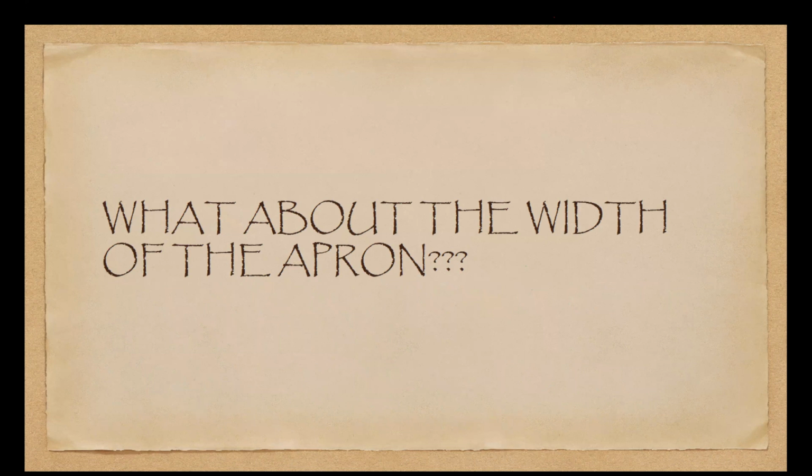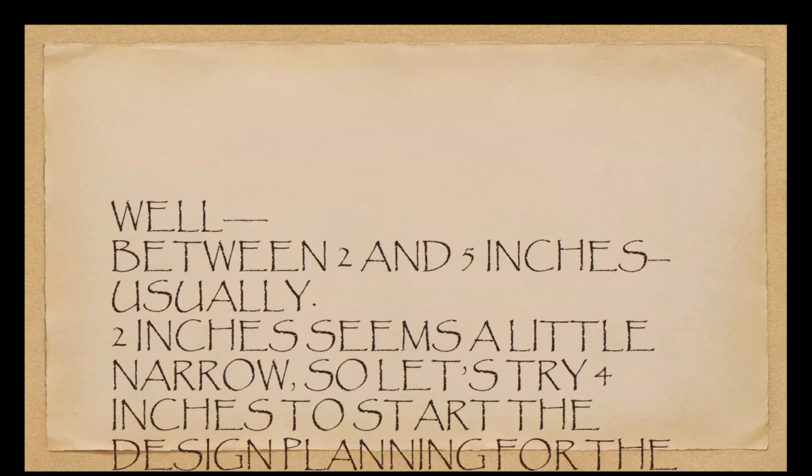Well, how about the width of the apron? How wide should it be? Usually an apron is between about 2 to 5 inches. 2 inches is really a little bit too narrow. It just doesn't offer much support either.